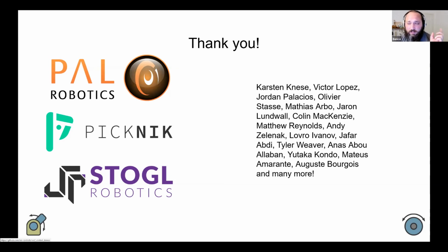I may have lied a tiny little bit when I said that that's what makes your RViz work, but the joint state publisher is what takes the joint states message and the URDF and then creates your TF tree to actually get you the animation and your TF tree in RViz. Although I think maybe the animation works directly with joint states. Probably it does.